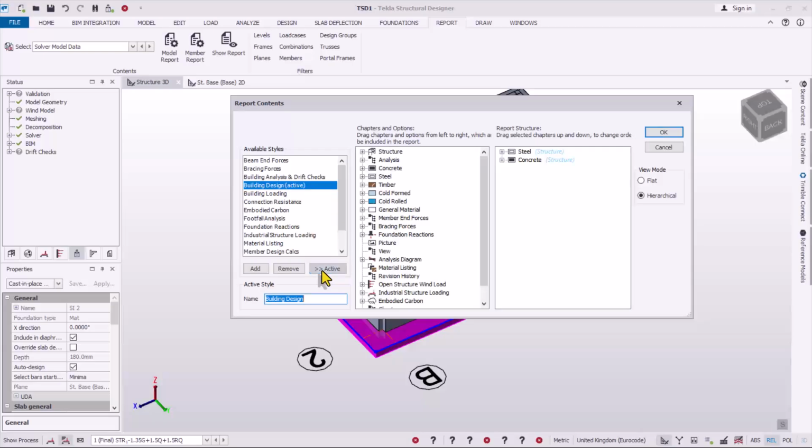active right here. Once you click on active, over here you see steel, and then you see concrete. We don't need steel, and we don't really need all of the concrete elements. From here, click on this plus sign, and then you can expand the wall from here. We need the wall detail calculations report first. We also need slab, so we come back to generate for reinforced concrete mat slab successfully. Click on the OK option.